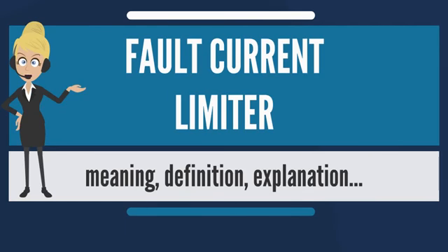If it is AC, then there will be a steady power dissipation from AC losses, superconducting hysteresis losses, which must be removed by the cryogenic system. An AC FCL is usually made from wire wound non-inductively. Otherwise the inductance of the device would create an extra constant power loss on the system.